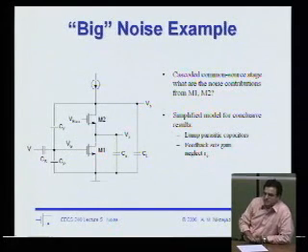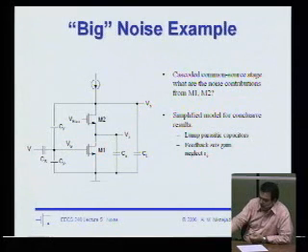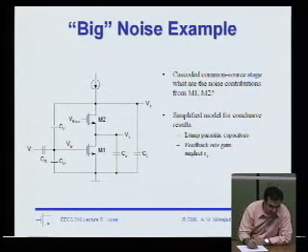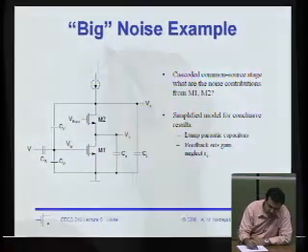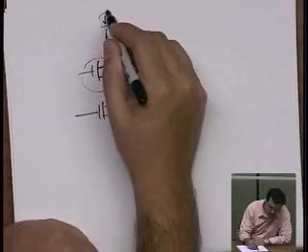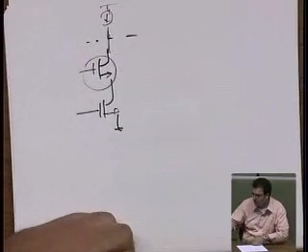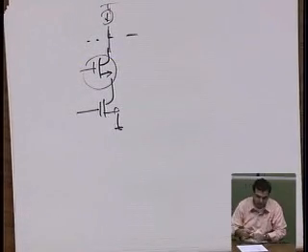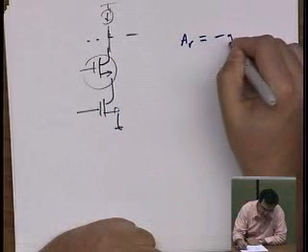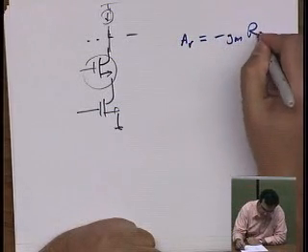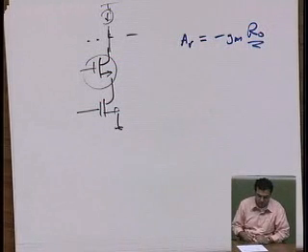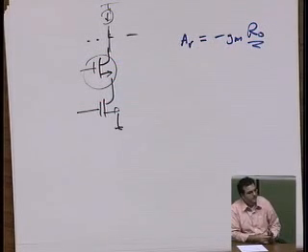So what's the advantage? By GMR? Yeah, exactly. It gives us really good gain. So a cascode amplifier is really a 2-stage amplifier, right? So what we're doing is we're using a current buffer which lets us go into a domain where we have very high impedance, as Toda is pointing out to us. So we have very high impedance at this point, so we know that we have a very large voltage gain because RO is large, right? What are some other advantages of this circuit?